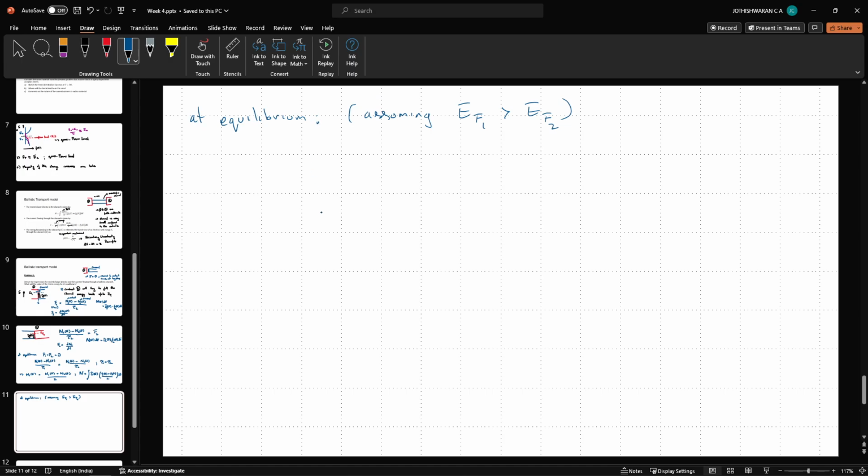Okay. So what will happen is, at equilibrium, exactly up to the midpoint of these two energy levels will be filled. Anything above that will be immediately taken by the channel, taken by contact 2. Anything below that, of course, the contact will be taking, but up to that level, contact 1 will be able to supply, which implies at equilibrium, EF for the device will be (EF1 + EF2)/2.